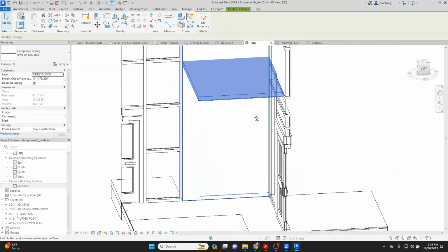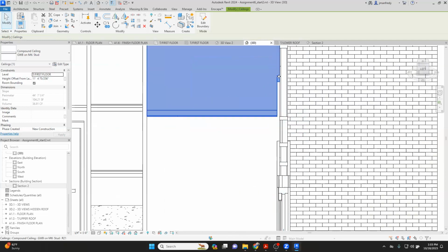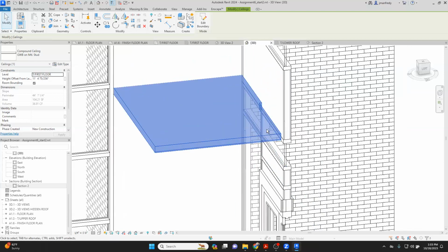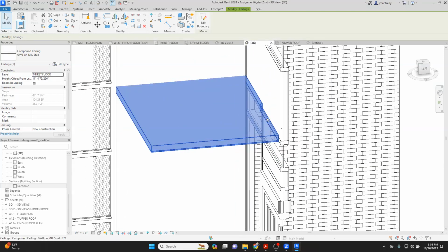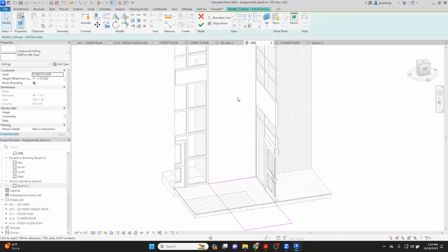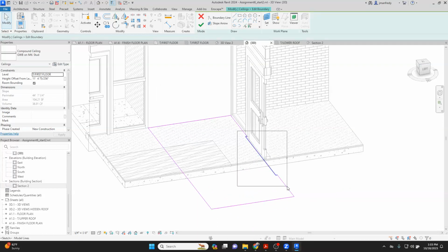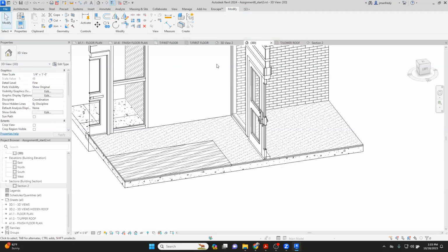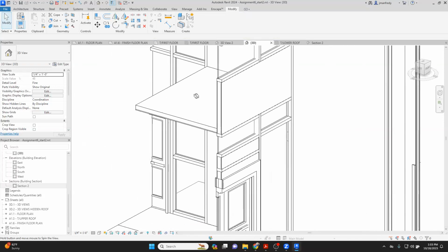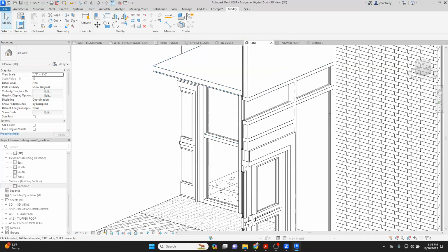It looks like this jog that we're drawing here actually belongs way down here above the doorway. It didn't actually belong up here. So honestly, I would probably get rid of that jog. Edit boundary. Erase the lines you don't need. And then trim it and make it just a simple rectangle. Because it doesn't jog the way I expected it to. This little bump out here above the doorway made me think there was a jog, but there is no jog. This wall is flat. So there's a ceiling up there above the entrance. They line up nicely.